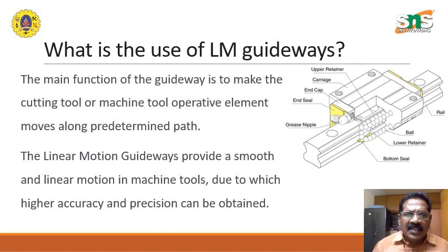Now, there's something called the LM guideways. The main function of this guideway is to make the cutting tool or the machine tool operative element move along a predetermined path. The linear motion guideways, or the LM guideways, provide a smooth and linear motion in the machine tools, due to which higher accuracy and precision can be obtained. We can see the diagram of this.